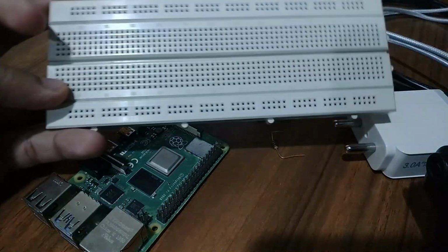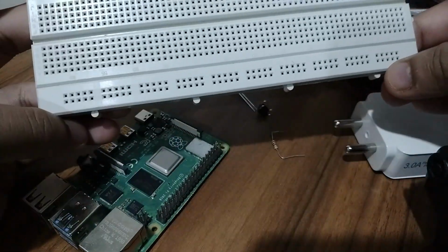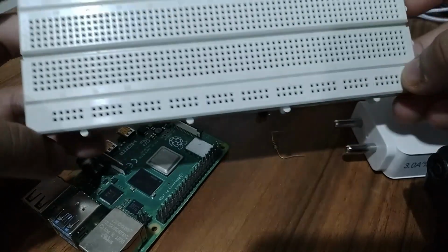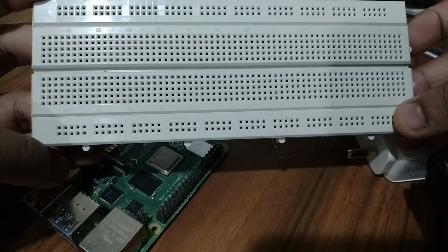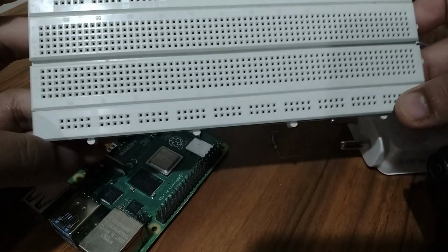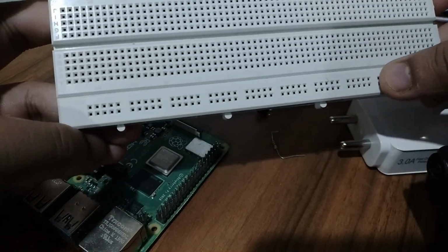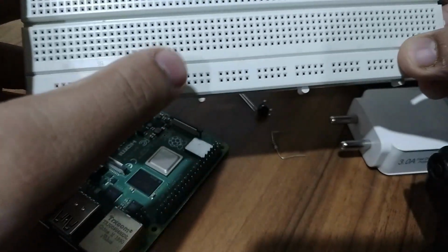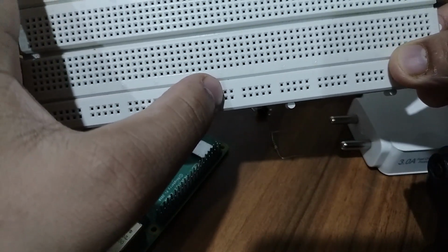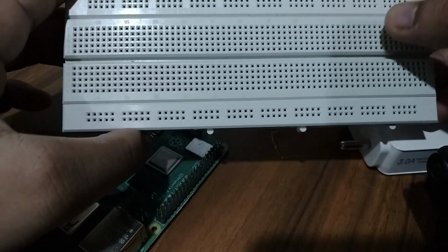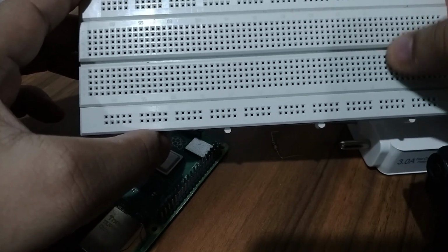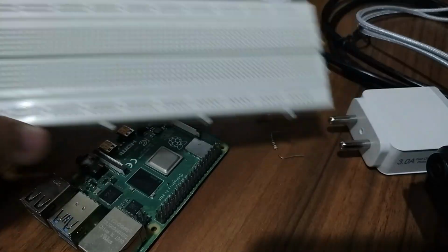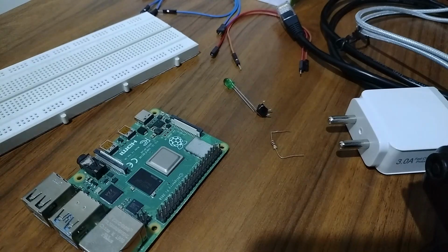This is your breadboard. I will tell you about the breadboard. Here are two terminals and here two. These are used for a common VCC or a common ground. These 5 are connected with each other, and the remaining 5 are connected with each other horizontally. Over here you mount your components, and these are shorted vertically. Now let's move on to the schematic for this tutorial.